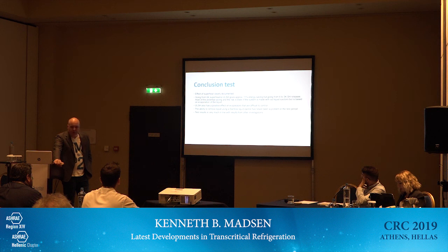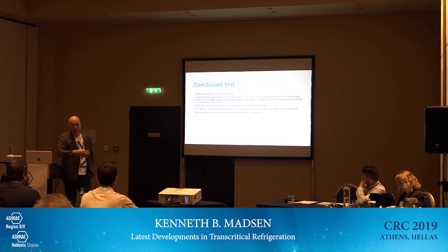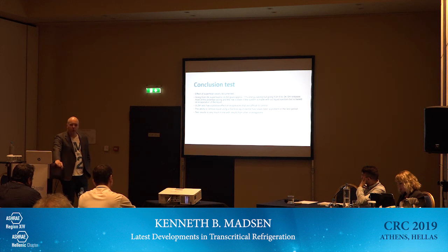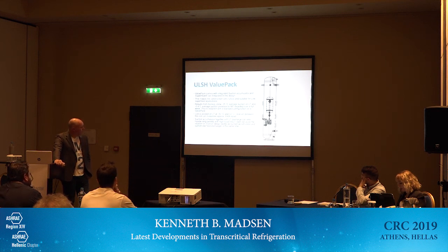One of the other things we actually see is that typically the evaporators that we have difficulty controlling, which is usually the ends of gondolas and stuff like that, when we use ultra-low superheat, they're actually a lot easier to control. So they're usually not the ones showing up as the most common case. That's also one of the interesting things, that suddenly the problematic ones are not so problematic anymore. Yeah, so that's it on the German side.